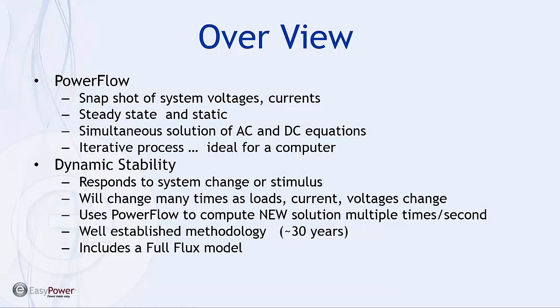One of the obvious side benefits of conducting an arc flash study is that the database we have built is the ideal representation of our electrical distribution system. That means we can take the data and produce a PowerFlow or load flow study relatively efficiently. The load flow is the result of the simultaneous solutions of the DC and AC equations of the elements in the system, and because they affect each other, this requires an iterative process, which makes it ideal for a computer application.